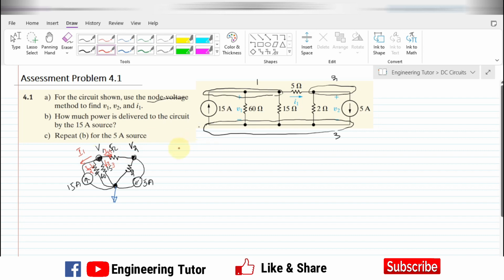Let me do all of this calculation for V1 in red color. For V1, I1 plus I2 plus I3 plus I4 is equal to 0. This is by the application of KCL. According to KCL, the sum of all the currents flowing away from a node is equal to 0. So what will be the value of I1?